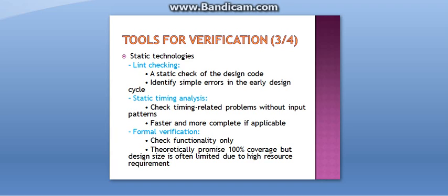Next is formal verification. It checks functionality only. Primary applications are equivalence checking and model checking. It solves the completeness problem in simulation-based methods. Formal verification cannot handle large designs due to its high complexity. Theoretically, it gives promise for 100% coverage, but design size is often limited due to high resource requirements. It is valuable but not a general solution.